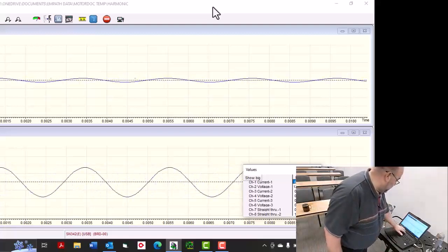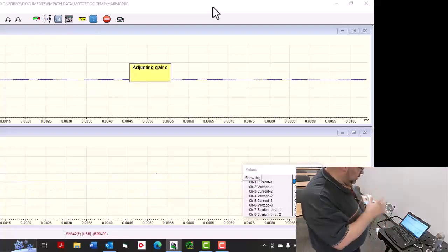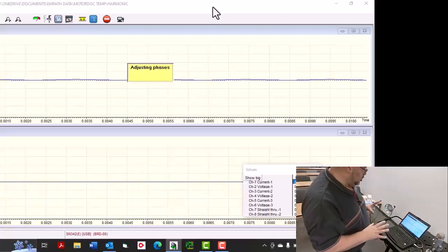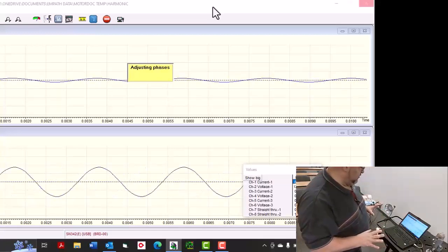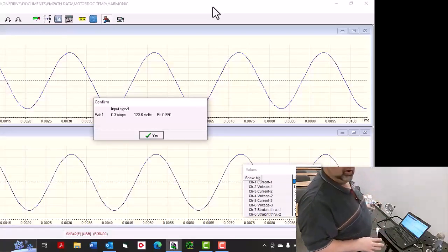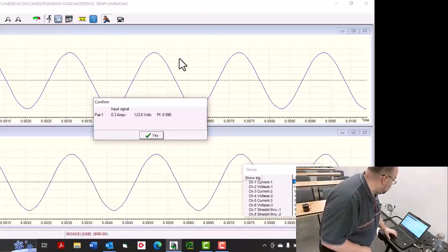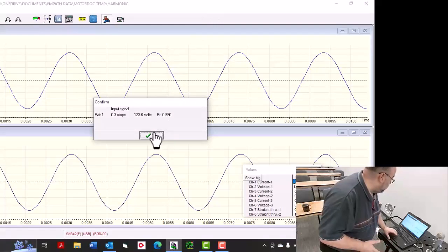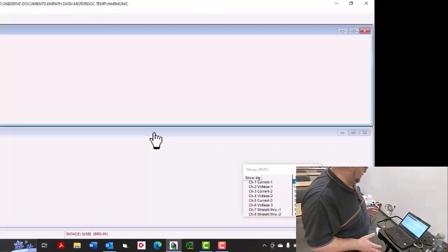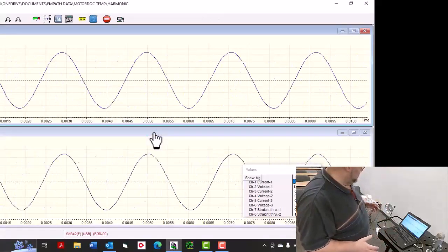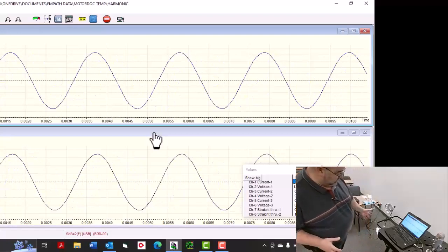Okay, I'll go ahead and zoom in, plus we're going to see the power factor, which will give us a good baseline for whatever the power factor is for the system before we look at the other one. Then we're going to talk about what true power factor is. So power factor 0.990, that's associated with the building, because it's basically resistive.